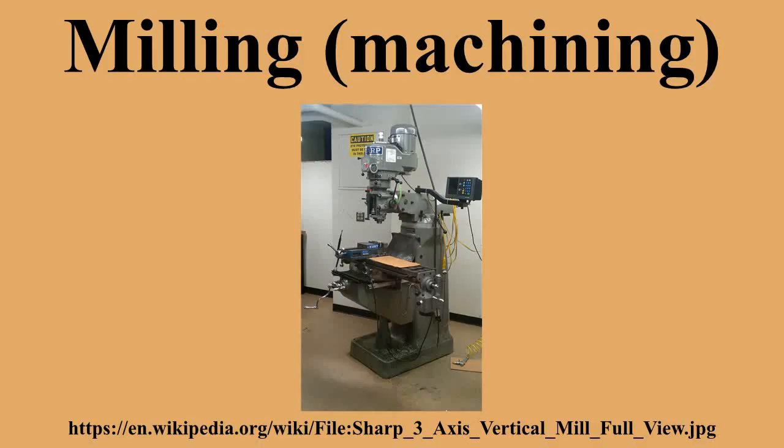The distinction, when one is made, is that a machining center is a mill with features that pre-CNC mills never had, especially an automatic tool changer that includes a tool magazine, and sometimes an automatic pallet changer. In typical usage, all machining centers are mills, but not all mills are machining centers. Only mills with ATCs are machining centers.